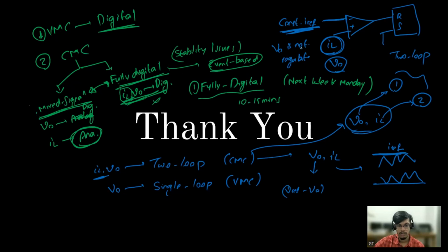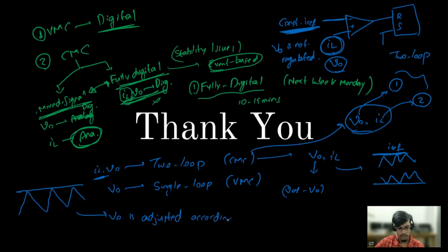Sir, what will happen if I use only single loop control then? Then you can give constant I reference as well. So if you want to use single control loop, you have to give constant I reference. So I reference is constant, IL will be accordingly, and V0 is adjusted accordingly. So you have no control on V0. If your V0 is to be 1 volt, it may or may not be 1 volt. So V0 is adjusted accordingly and you don't have any control over it.